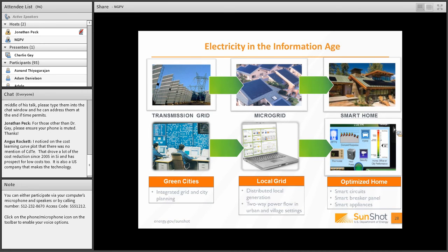And that information can be useful all the way up to the operator of a transmission grid in being able to manage the system voltage and system frequency. And some of the inverters that are now commercially deployed could essentially perform services 24/7, because even though they might not be used to convert DC to AC electricity, they can be relevant to stabilizing the voltage and frequency response.